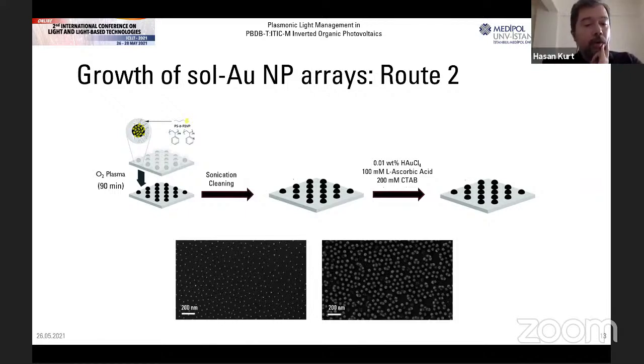For gold, it was in 2016. We actually did that in my thesis work. Technically, the oxygen plasma that we use is like 30 watts, and the pressure was around a torr. So technically, it was a chemical oxygen plasma. It wasn't a physical one. So it only reacts with the polymer structures and only reduces the precursor. We tried different plasma times, and we didn't have any problems for the gold. We had some problems with different nanoparticles, for example lithium fluoride.